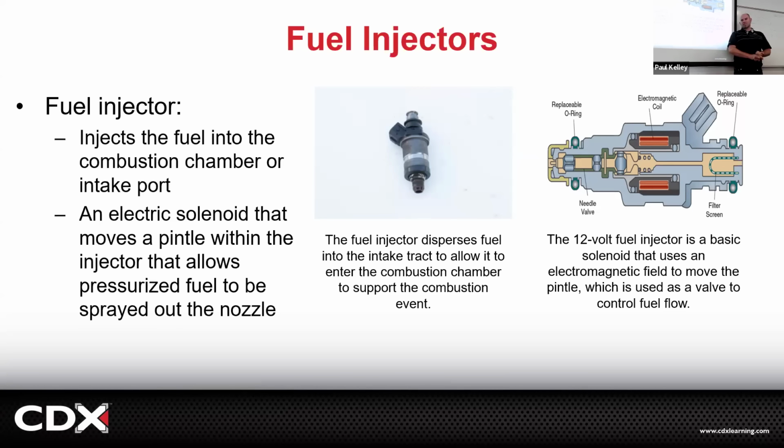So I had a homie with the Neon. You guys remember those? A Dodge Neon. Junk. Yeah, it was junk then. It was junk when you had it. It was junk when he had it. Like every 3 months or so, he'd end up with horrible misfires. And every 3 months or so, we'd pull the fuel rail out, take the injectors, tap them upside down, and rust would come out of the top of that screen. How it was making it past the fuel filter, I don't really know. Maybe it was the inside of the fuel line. I'm not really sure, but we cleaned it all out. And literally every 3 months, he kept cleaning them, putting them back in. And then eventually those O-rings ripped. So it ended up with a fuel leak.